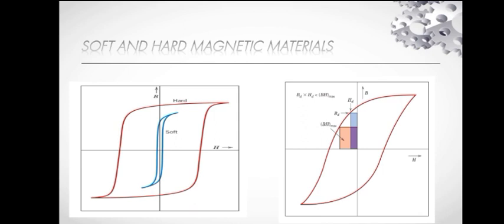So, in this figure, it shows the magnetization curve that displays hysteresis within the second quadrant. Here, two BH energy product rectangles are drawn. This is our energy product, denoted as (BH)max. The area of the rectangle labeled (BH)max is the largest possible, which is greater than the area of the one defined by the B_d and the H_d.